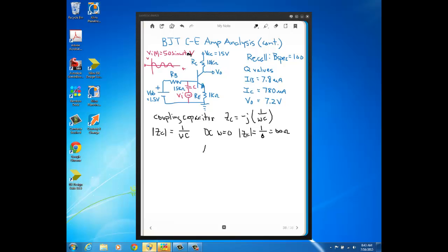Now for AC, ω is going to be something other than 0, because with AC sources you do get an oscillation, as you know. And if we make that source frequency times the capacitance large, ideally infinity, well, now you're going to have 1 over a big number, ideally infinity, and that's 0. So a coupling capacitor blocks DC, because it acts like an open to DC, and to AC, it allows it to pass through virtually unimpeded, because ideally it acts like a short.